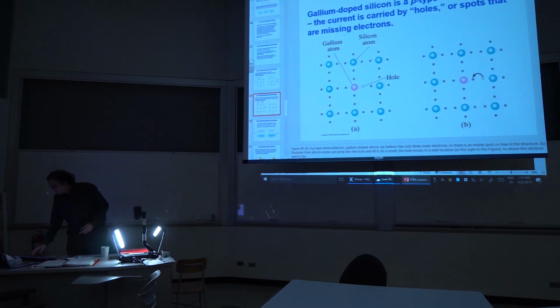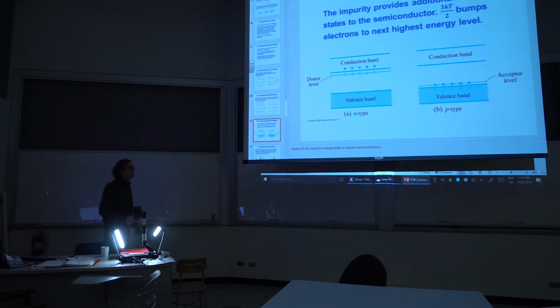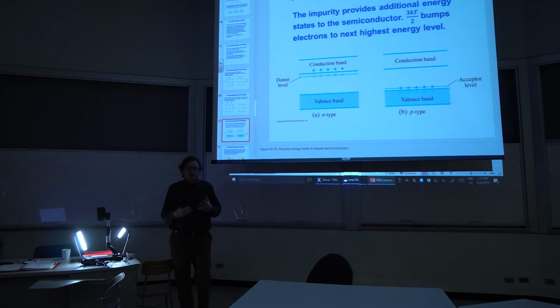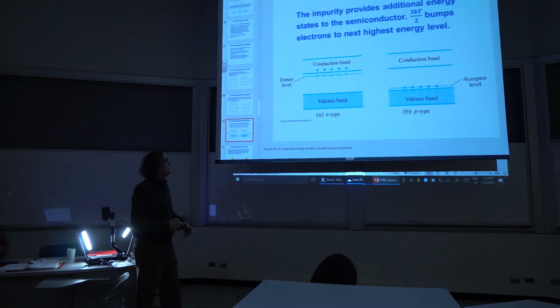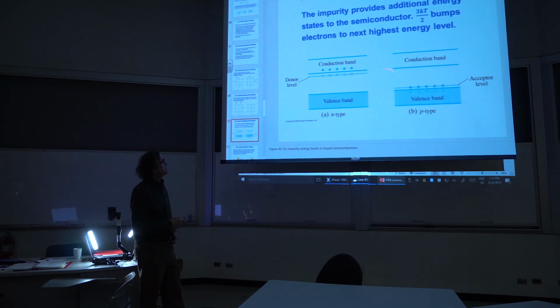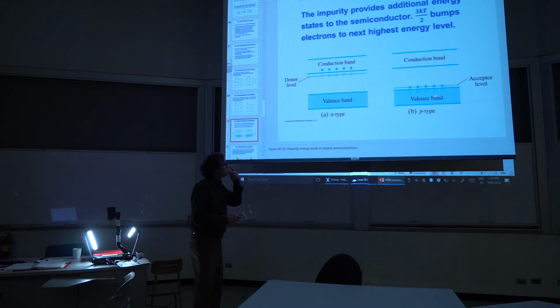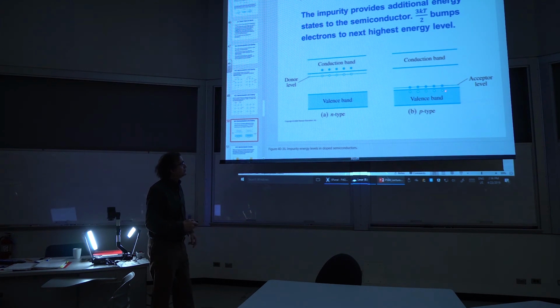So in terms of the band theory of solids, we have a new energy level, which is similar to the arsenic for the n-type, except in the p-type we have created what's called an acceptor level, which allows electrons to jump from the valence band into a slightly higher energy level, called the acceptor level, and that distinguishes the two types.